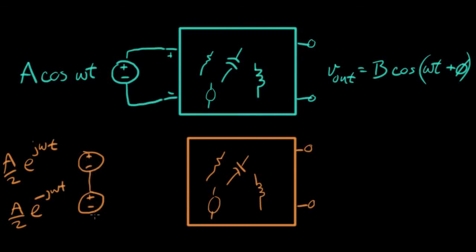And if I add those together, like that, now remember the equation we just looked at, Euler's formula, says that cosine equals that. The voltage here is exactly the same. And all we've done is describe the same exact cosine waveform as these two imaginary exponentials.